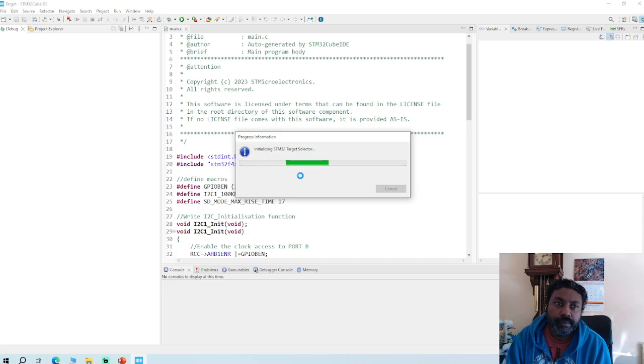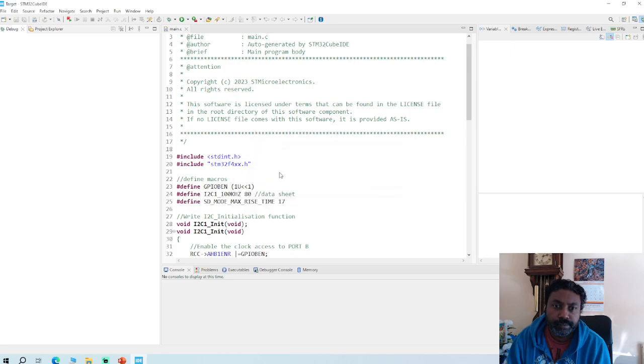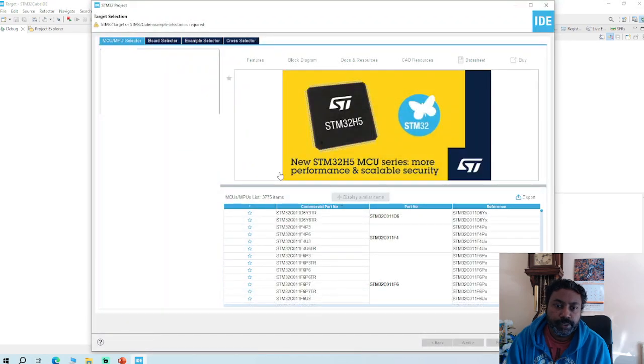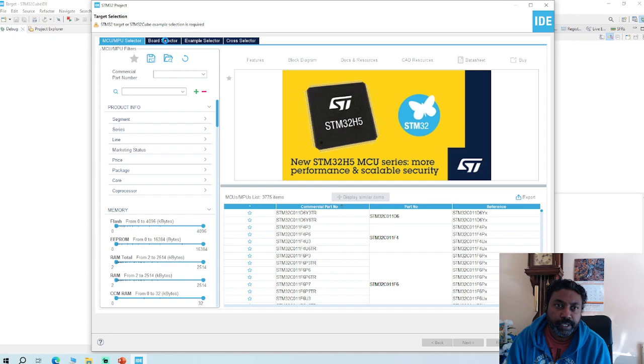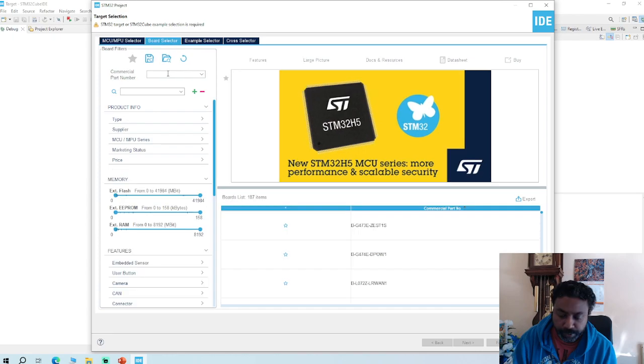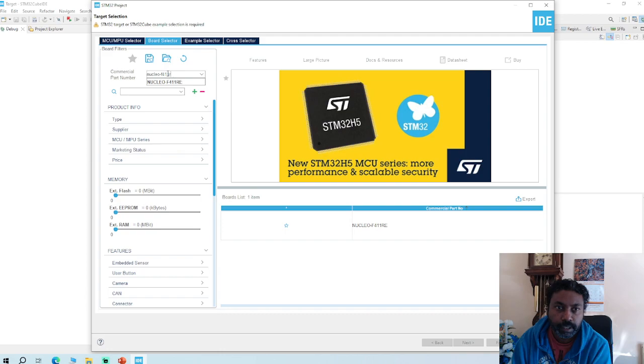I have gone ahead and done all this. I'm just taking you through it in case you have forgotten how to do it. So this is how you have to do it. Once it allows us to choose the board selection, you need to go here to the board selector, you know which board you are using. So I'll type Nucleo F411RE and choose that board, RE, and then click next.